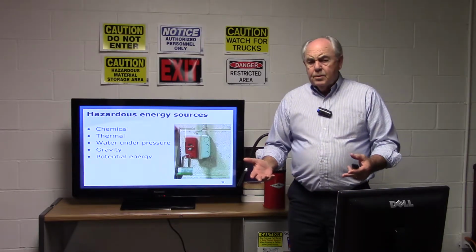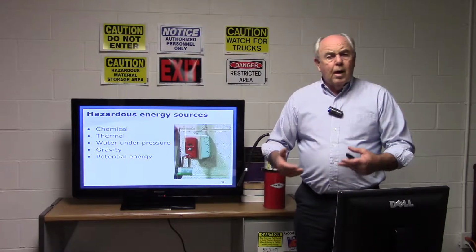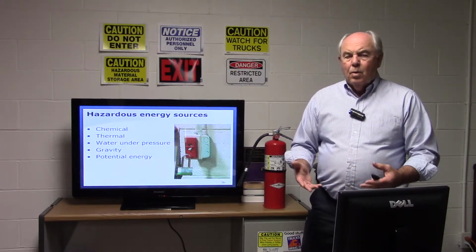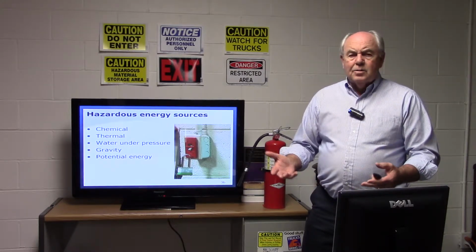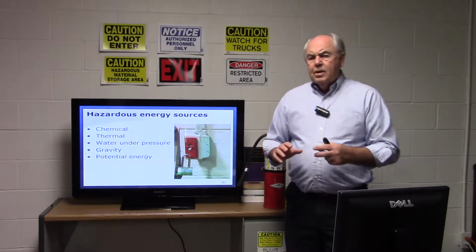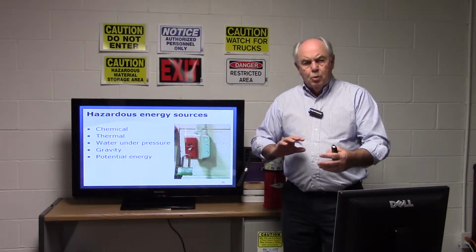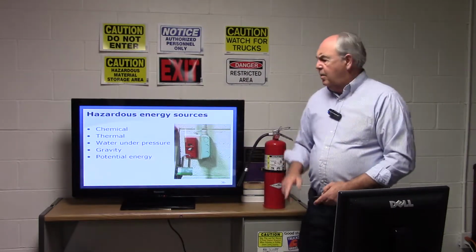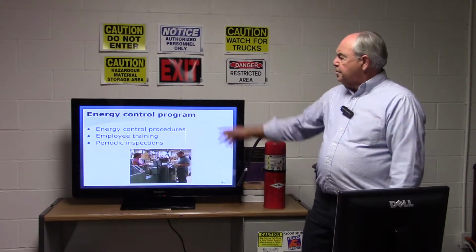Sometimes the temperatures of the oil or hydraulic fluid or whatever chemical is in that line can be as hot as 320 degrees, and you don't want that spraying in you. So making sure that you remove all the pressure or you de-energize whatever you're working on is critically important.